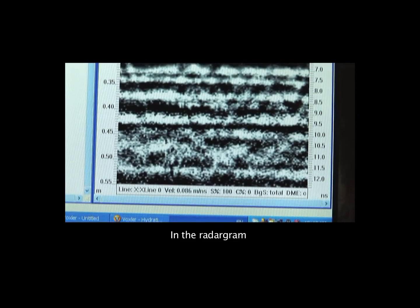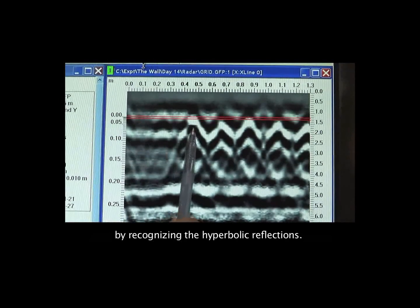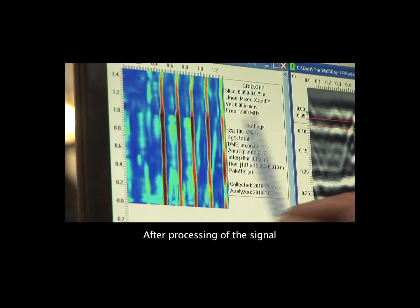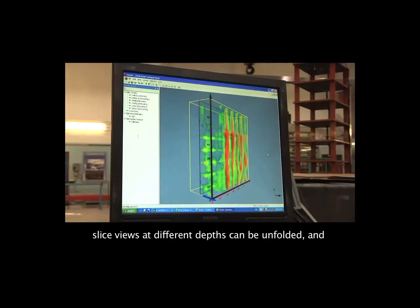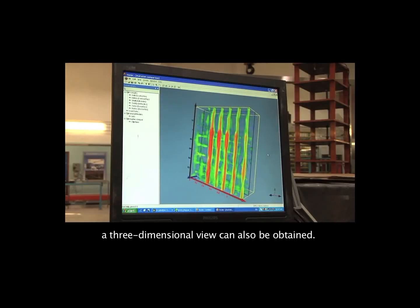In the radargram, we can locate the position and depth of the steel bars by recognizing the hyperbolic reflections. After processing of the signal, slice views at different depths can be unfolded, and a three-dimensional view can also be obtained.